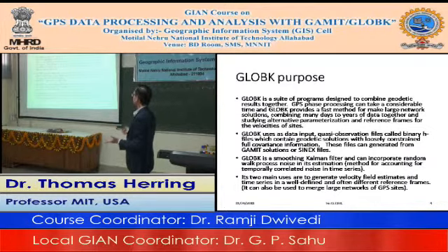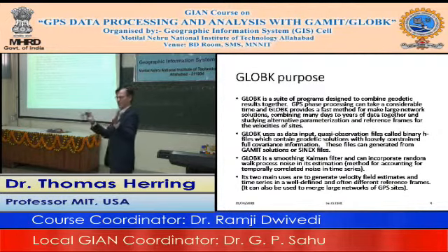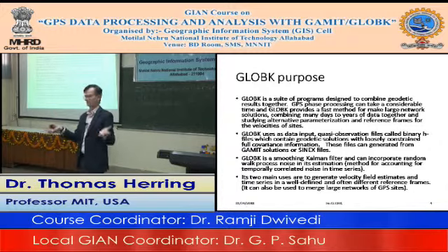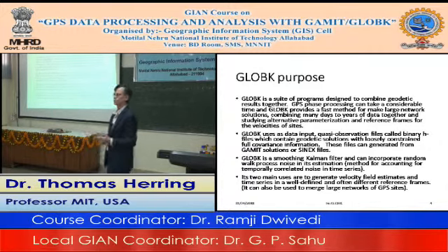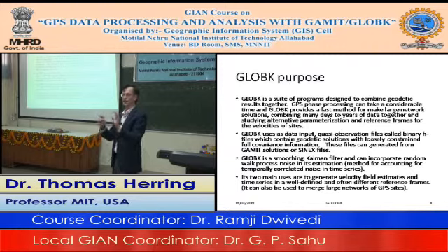And so the phase processing from GAMIT, as you can see, those runs we were doing, we're using 10, 11 stations, and they're taking 10, 15 minutes or something, maybe less than 10 minutes to run. But the runtime on GAMIT is going to go as the cube of the number of stations. That's primarily because it's dominated by inversion of the normal equations, and that's going to increase linearly in size with the number of stations, and matrix inversion takes a cube of the size of the matrix. So when you're dealing with 50 or 60 stations, you're looking at 1 to 2 hours to do it. So the GLOBK processing can be done much faster.